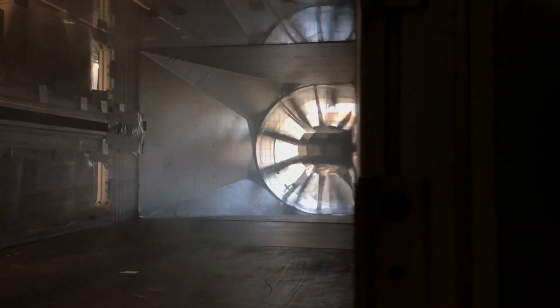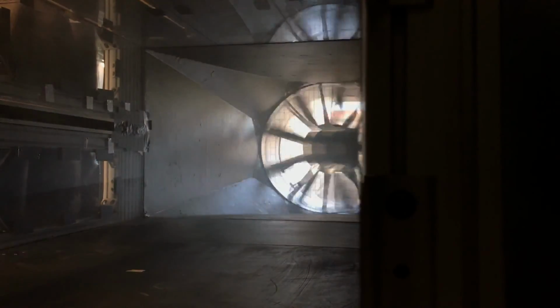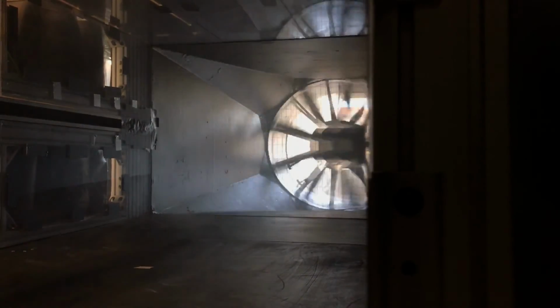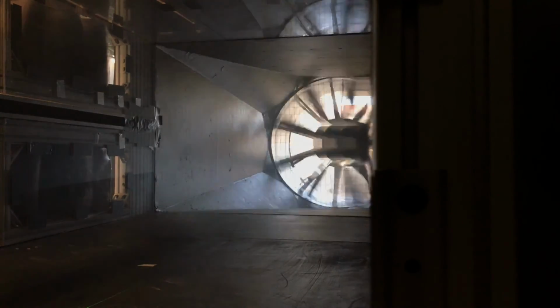This knowledge served as a foundation going into Lab 3, where more complex flow visualization occurred due to an object placed in the test section. The object in question was a cylinder with pressure ports mapped out along its surface. Although a cylindrical shape is relatively simple, when placed in a flow field it can produce intricate flow regimes.